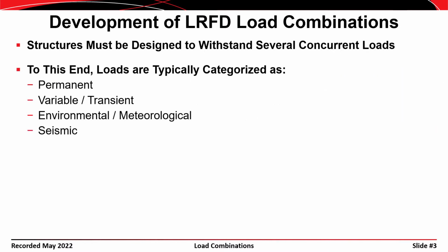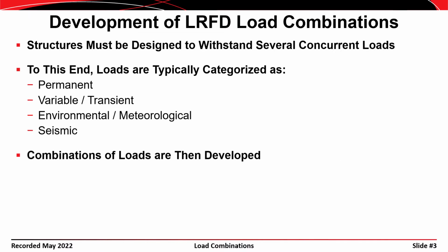To this end, we categorize our loads as permanent loads, loads that are either variable or transient, loads that are environmental or meteorological, and at least for my purposes, I'm going to categorize earthquake loads as their own entity. I think Tally and maybe even Finella categorize them as environmental loads as well, but I'm going to treat them a little bit differently.